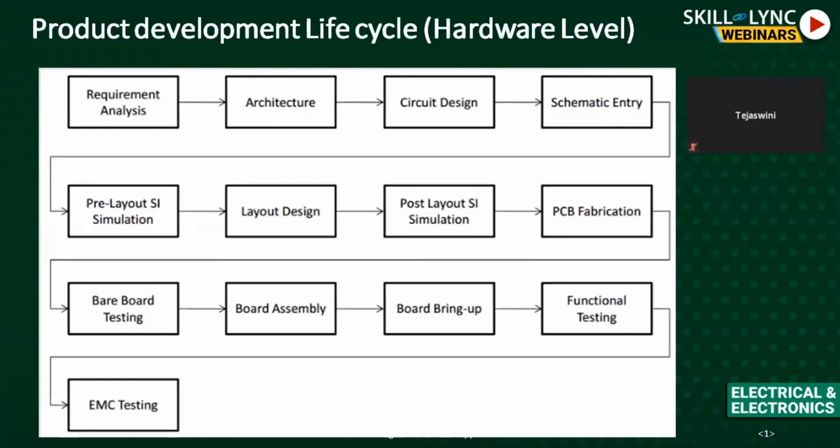If the number of components is large, say 1000 or 2000 components, the bare board testing is a part of PCB fabrication. If it is a smaller number of components, we do it in house. And then finally the board assembly, then the board bring-up, which is really a challenging one, because you have all the components populated on the PCB. Now the board has to work.